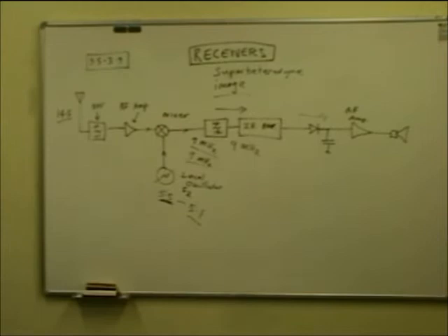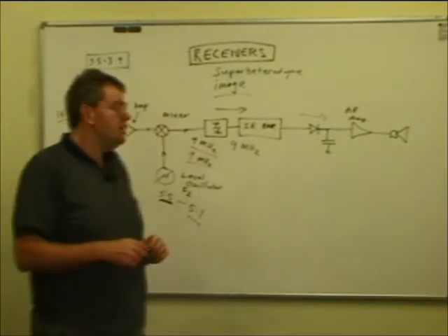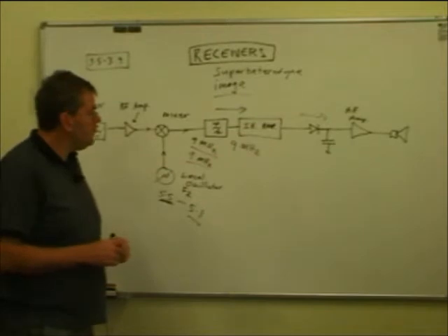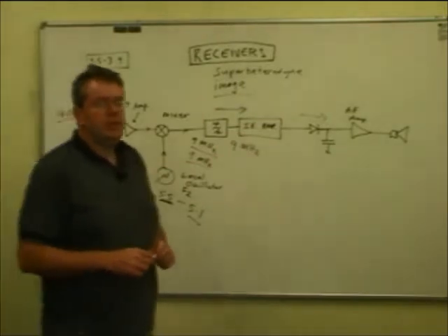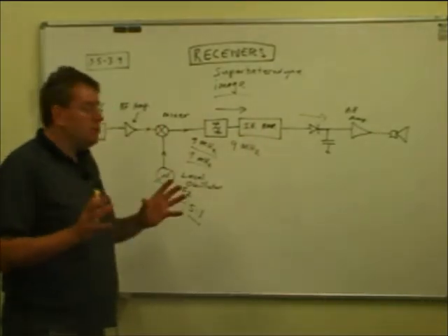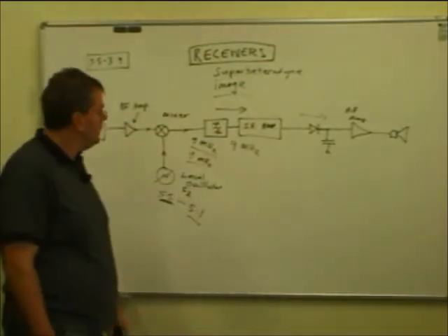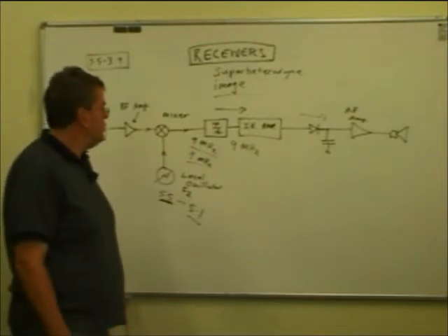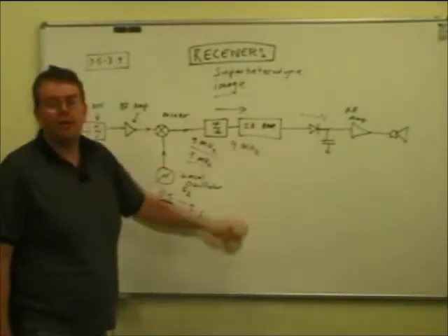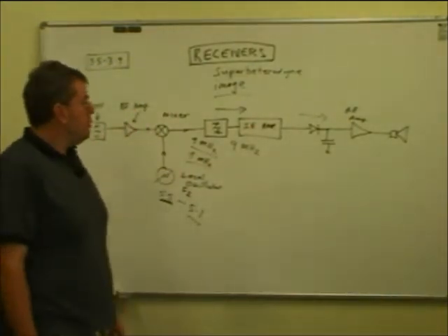Okay. Just another thing we need to talk about is the frequency we choose the IF, the intermediate frequency, to be at. We can, for all intents and purposes, choose any frequency we like. Generally, we choose a frequency at which we can make a nice narrow filter operate. In the early days of receiver construction using superhets, you could only really build a narrow filter IF amplifier arrangement at quite low frequencies, typically only a few hundred kilohertz. And that causes some problems, and we'll just show you why.